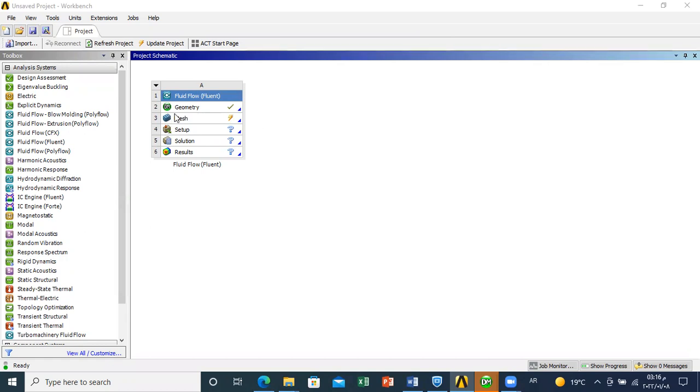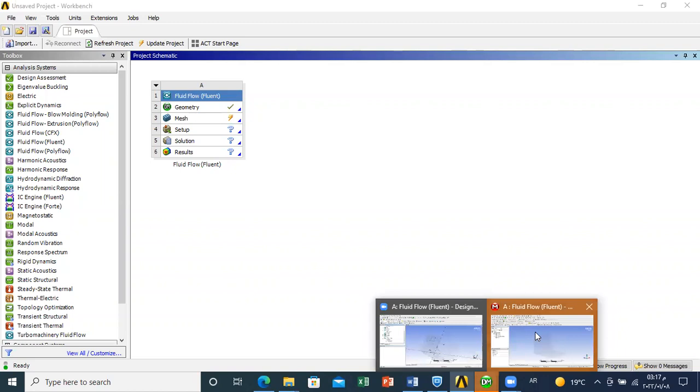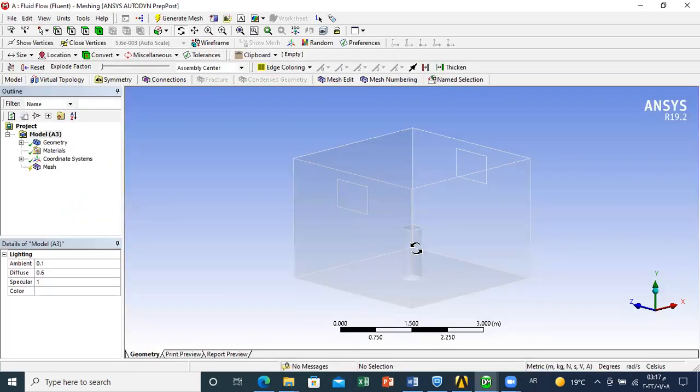results, etc. So this is one of the most important parts in CFD, because if you don't have a good mesh quality, and we'll see how we can assess the mesh quality, you cannot have good results, and you might have divergence or unphysical results. Okay, so you double click on mesh after you are done with the geometry, and this window will open for you. So this is the space we considered in the geometry part.